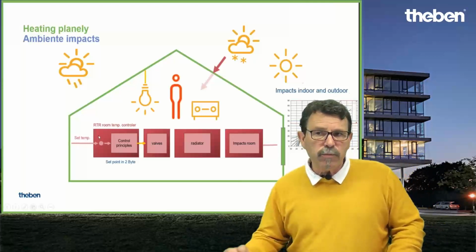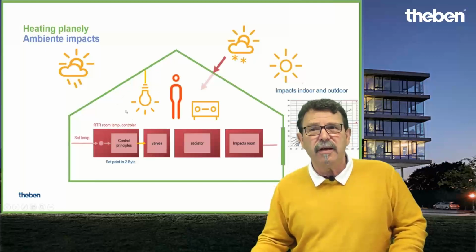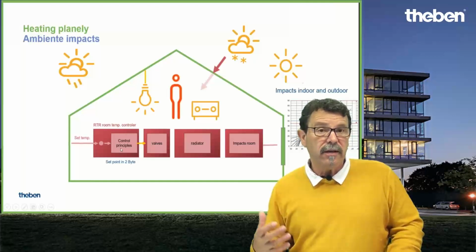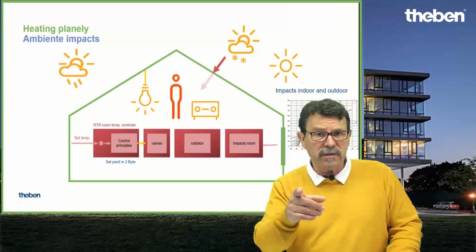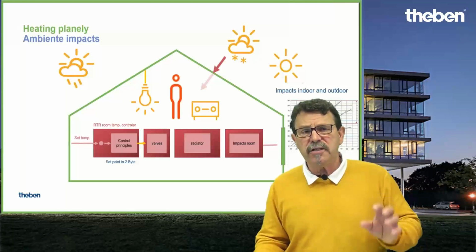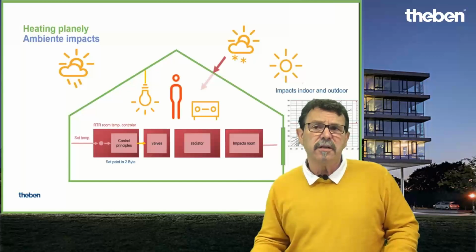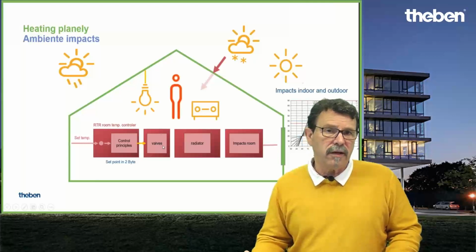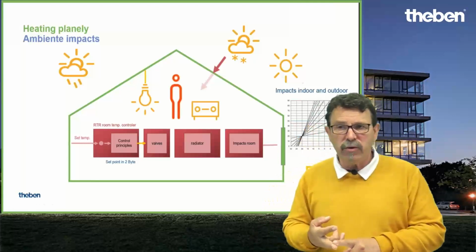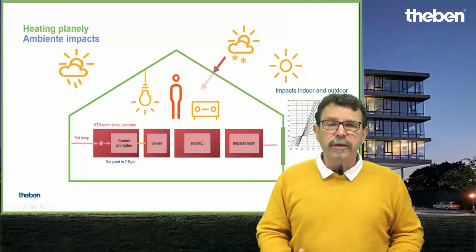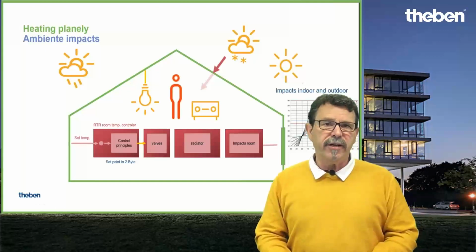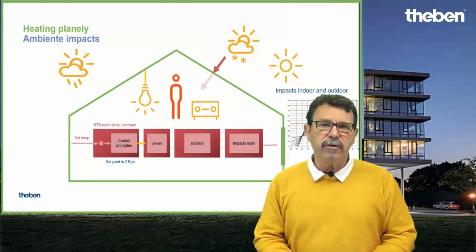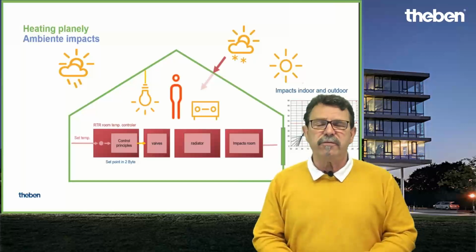This room temperature controller measures every second the current situation inside of the building. It knows the set temperature, your desired temperature, which you preset, and the difference is calculated as a heating value, which is given to the valves. Again, either a motor-driven valve or a thermal valve, and then we open or close a radiator, the flow forward, so the warm water flows into a radiator or underfloor heating, depending on the situation.